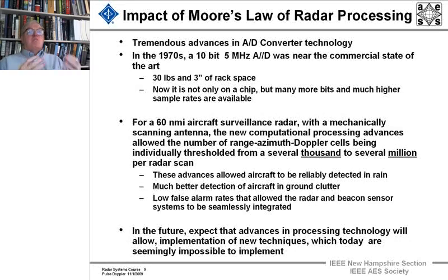I'm talking about algorithmic techniques. Now, what we're going to do is propose a specific set of weights for the entire radar. But some of the new techniques you can use are to measure, if you're familiar with these terms, the Doppler, I'll say it in lower level language, the power spectrum of the clutter in each range azimuth cell, and then calculate the optimum weights for that individual cell.